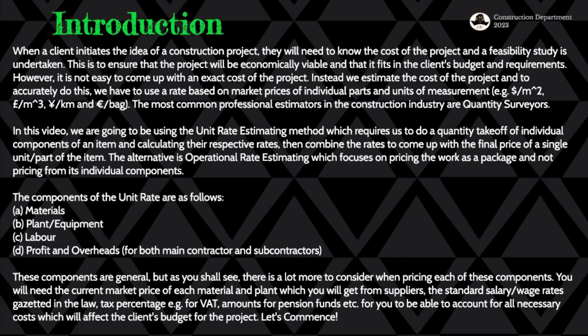If it's cement that we're going to be looking at in terms of this example, we'll need to do it in bags. We need to charge it in bags because the suppliers sell it in bags. If we need maybe the tar that's used on the kilometer of a road, we need to price it according to the unit of measurement that is used in the market to sell that tar. So if it's maybe tons, you then charge it in tons. Like concrete is charged in tons. So that's another unit of measurement for the mass of the concrete.